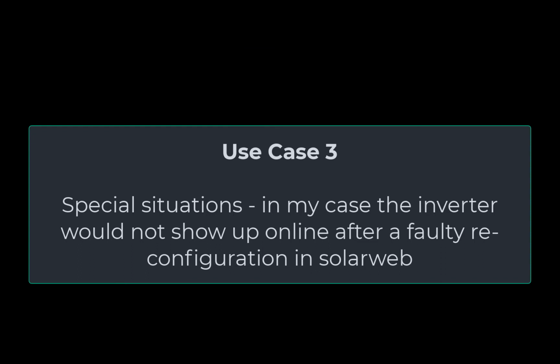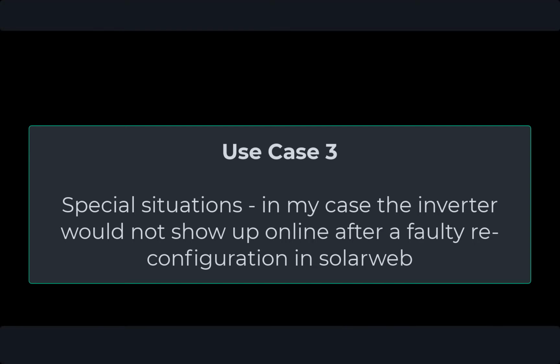My rather simple solution to this strange problem finally was to exchange the installed data manager with the data manager of a second inverter of the same type that I've just bought. After trying various things, that turned out as a working solution. There might be other reasons why you would want to check, reset, or update SolarWeb settings as well.